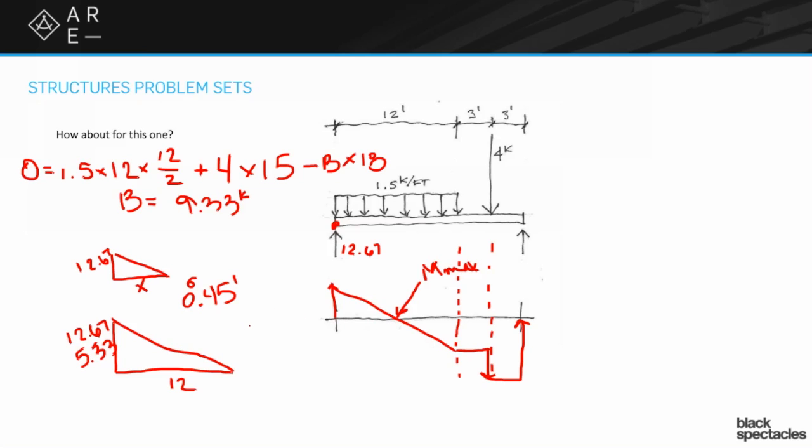And so that tells us our basic question, which was, where is the highest amount of moment? Correct. And we figured that out through a combination of using the shear diagram, understanding what the shear diagram was telling us, and then doing a fast graphic version of helping us understand where exactly that point of crossing is. But we also could have done a moment diagram. We could have done a sum of moments and then figured out distances. There's a series of other things we could start to figure out as well.